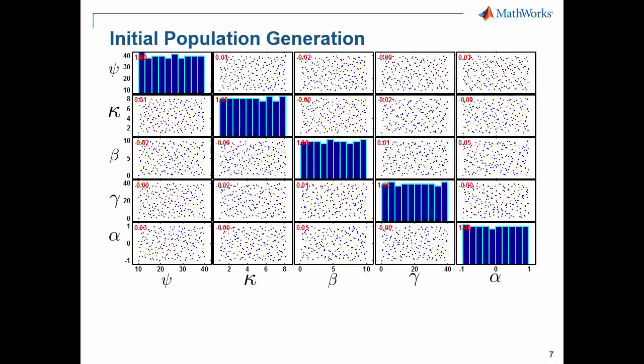So I just mentioned that the genetic algorithm will require or otherwise create an initial design candidate population. In the case of the HEV study, I used a Sobol quasi-random space filling routine from the statistics toolbox so as to maximize the available design space while ensuring an even yet non-correlative sampling of the specified design variables.